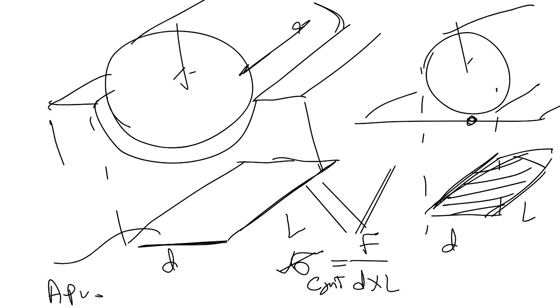I is the second moment of inertia. And Y, what is Y? Y is the vertical distance away from the neutral axis. It is the perpendicular distance measured from the neutral axis to the location at which you are trying to calculate your stress. Because we are not always looking, guys, for the stresses at the top layer and the lower layer.